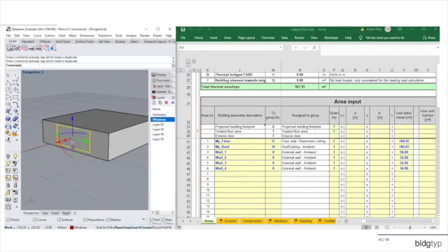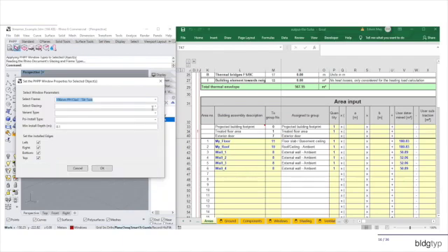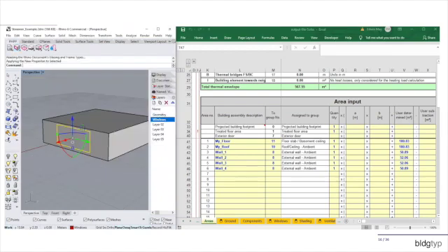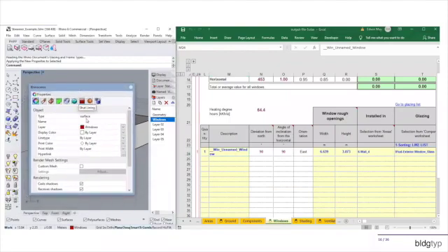We also get the complete EnergyPlus and PHPP model without any ambiguity as to the data source, which is going to simplify the data management and reduce our errors across the board. For instance, if we want to add a couple windows, I can very quickly just hook up a window here. I now have one window which is pushing through into the PHPP.